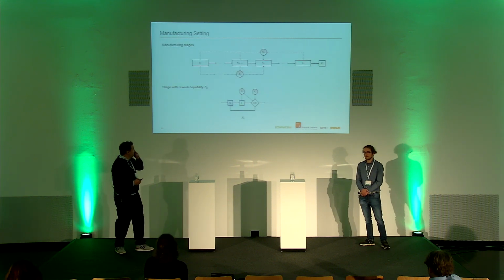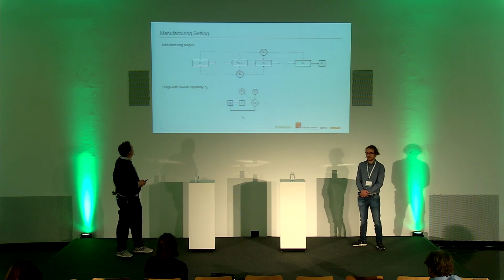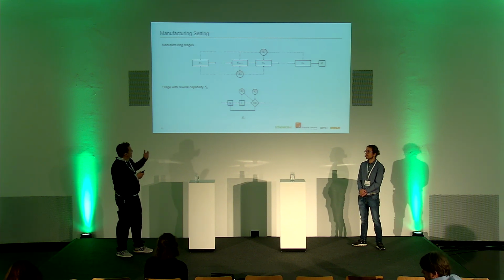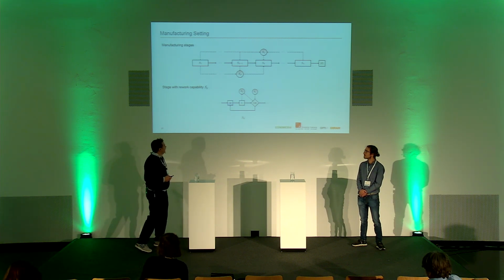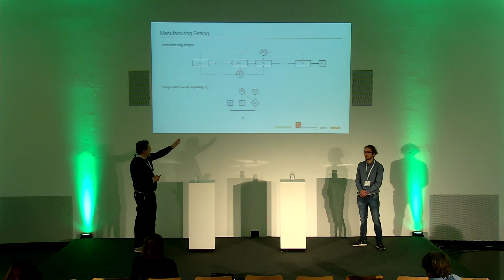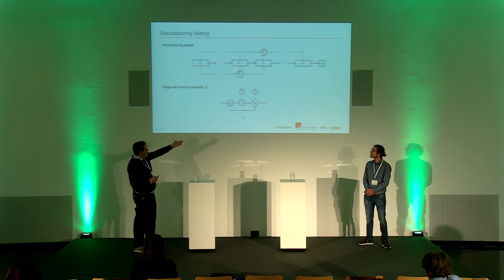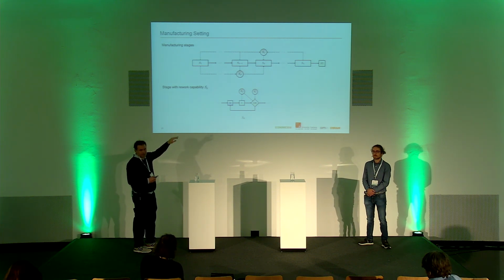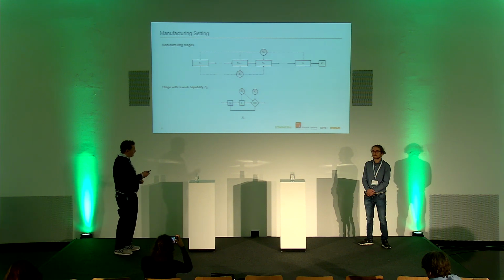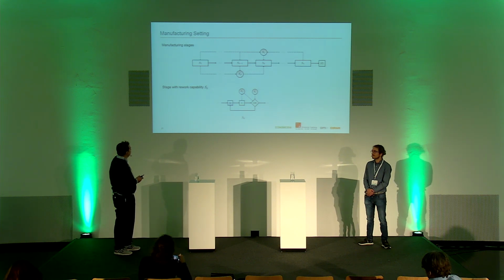So here, very high level, on the top you see the manufacturing stages. You have different kinds of stages in a linear process, and at each step there are certain characteristics, denoted X, which describe this state. Now in rework, we single out one step, S_k for example, and now we build in an inspection stage where we take some measures, and then we take a decision. And depending on the outcome, we either move forward, or we do a rework step, or in the extreme case, it's waste and cannot be rescued.